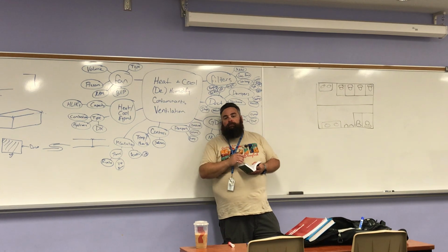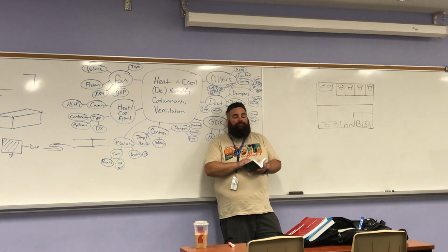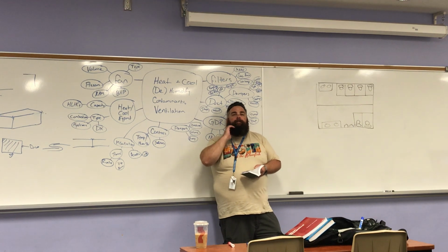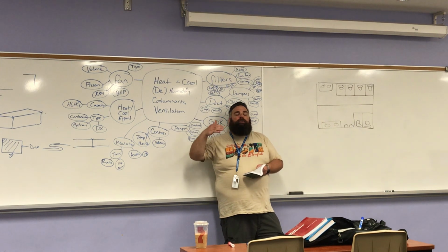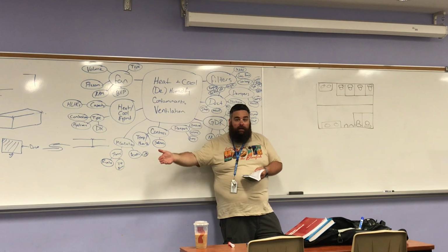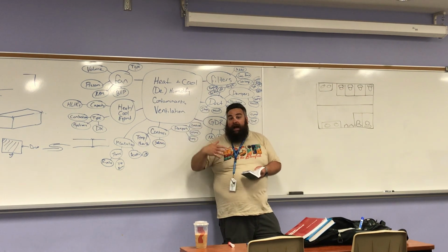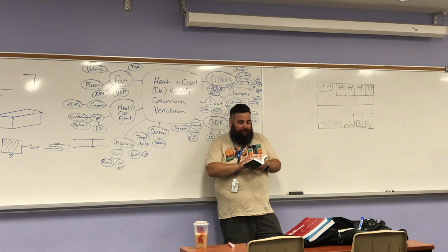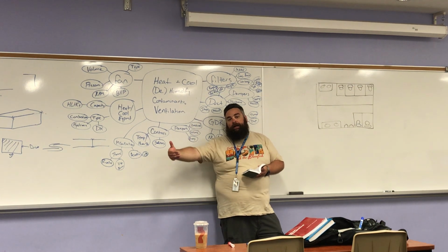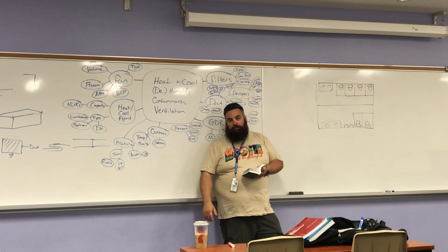What do you mean by class of air? So the class of air refers to the contaminants that are in it, and what that means is, can we put this where we discharge next to, how far does it have to be from an intake, and can we filter it and send it back to the space. So for instance, with class 2 air, we have a minimum of 10 feet between the discharge of class 2 air and the intake of outdoor air, okay?